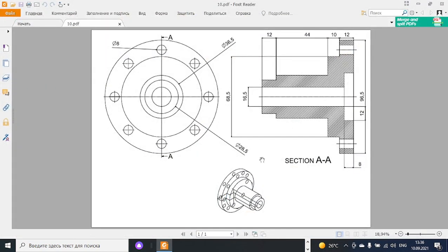Okay, here we have to obtain this element. Here you see the cross section of this element. As I said before, in the revolve function we always have to take care, as a first step, to draw the cross section. So we will draw this cross section in this shape, put all the dimensions as demonstrated here, and revolve around this axis until 360 degrees in order to obtain our shape.